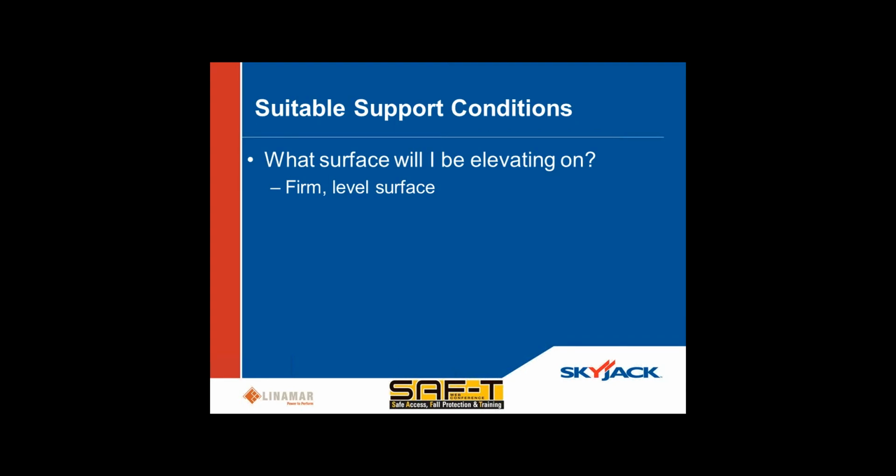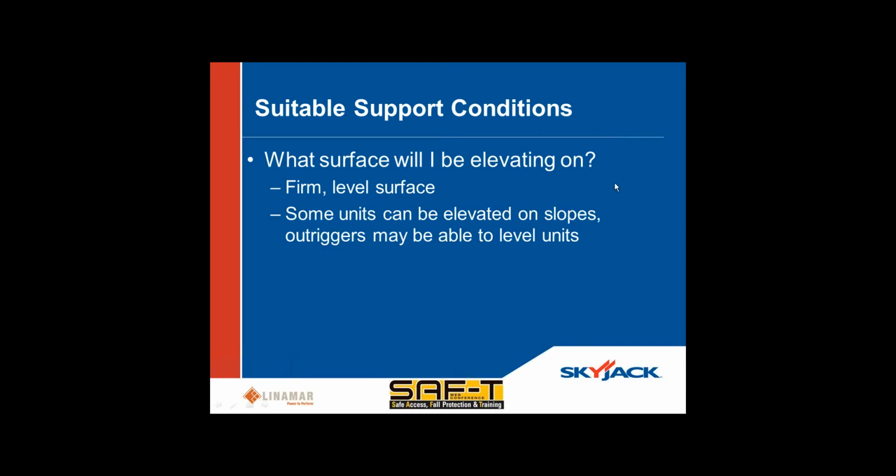There are some lifts that will allow you to level yourself, with the help of outriggers or even independent leveling of the lift itself. But in general, most of the time there are parameters in which you must achieve a certain degree of being level before you're able to elevate the lift. Some units, as I said here, I guess I got a little bit ahead of myself, can actually be elevated on slopes. And again, you may be able to use outriggers on certain units that have them and are allowed to use them to level the units to a certain degree.